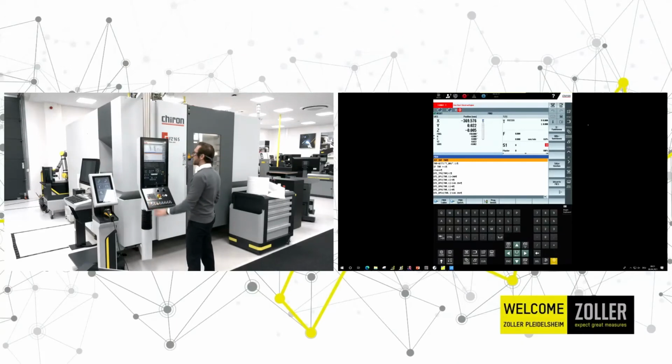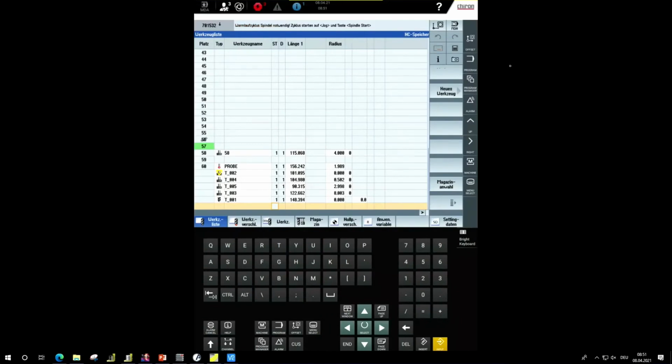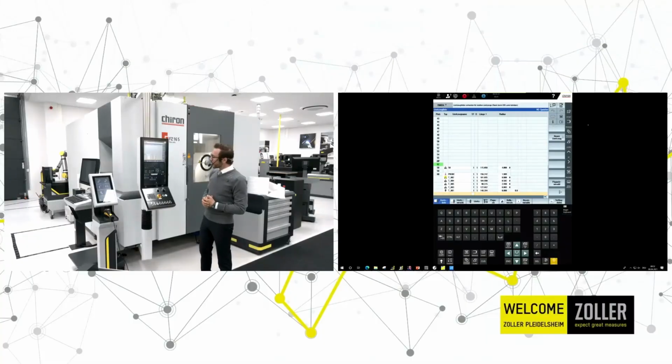And I hit the cycle start, and now with this loading program, if we did everything right, the tool data should be inside the magazine. So quick and easy, no chance to make mistakes. And now we see first of all tools are in the magazine.